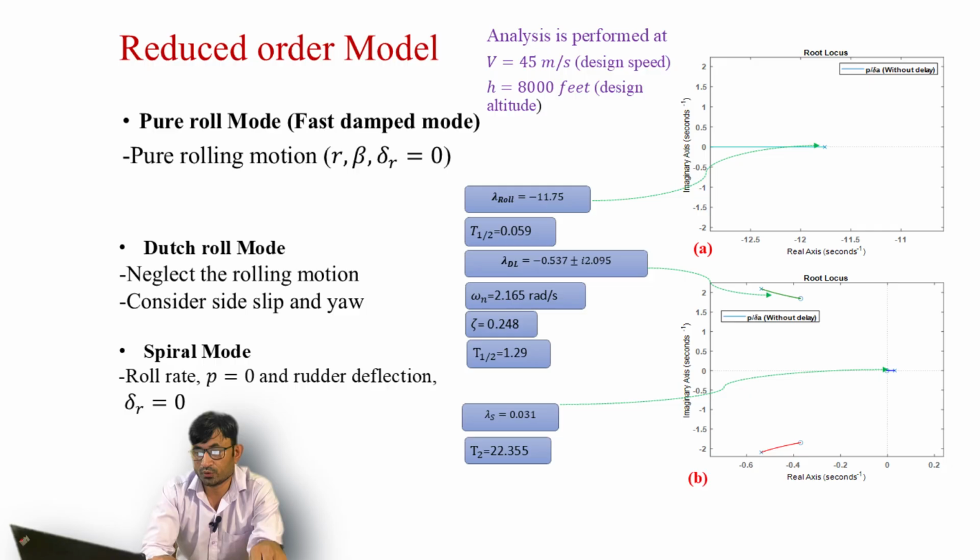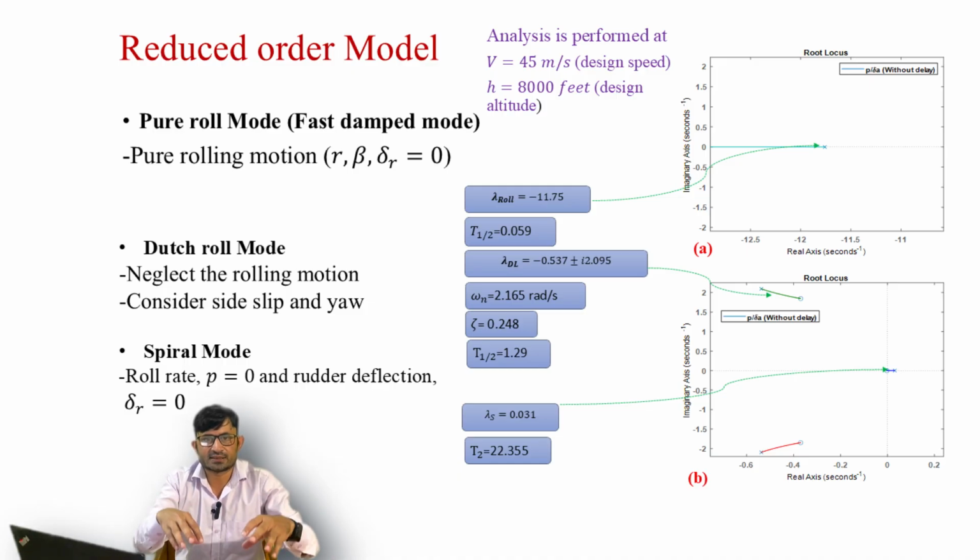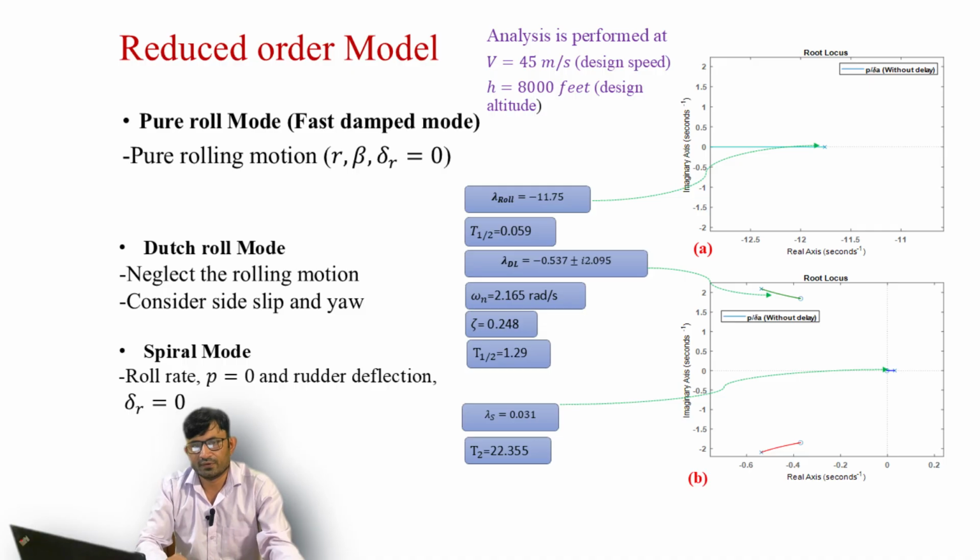So how can you get this mode? By setting roll rate equal to 0 and rudder deflection equal to 0. However, we will discuss it more mathematically and physics-wise in the future, because when we cover aircraft directional dynamic stability, we will see this kind of slide again and try to give you more feeling, since at that time we will estimate the damping derivative in the yaw case and other derivatives. Then we will see them together as lateral and directional motion.